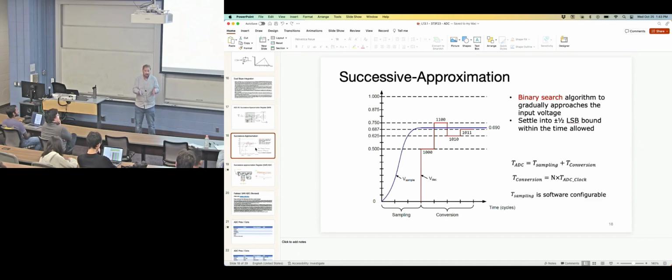You could do that. You could totally make circuits and algorithms that say, aha, as soon as you converge on an answer, stop the ADC read and then send an interrupt and alert the core to come and grab the value. You could totally do that. But because you don't know what the input analog voltage is, you may save a few clock cycles here or may not save them later on. So now it becomes a nondeterministic amount of time that you're saving, and that's just usually not that valuable in an embedded system. So going from 8 clock cycles to 16 clock cycles, not that big a deal. Does that make sense? Okay.